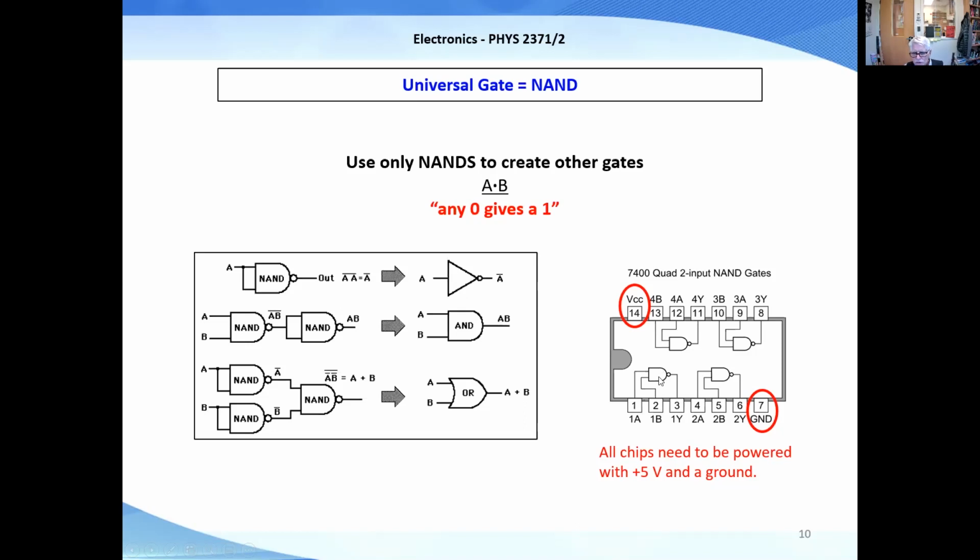Even though there are many transistors, several transistors at least, inside any of the gates, the gates need some voltage to operate on, independent of what voltages you're putting on the inputs here. So you always have to ground, like pin 7, and put a voltage 5 volts in on pin 14. Then you can use any of these four gates here.